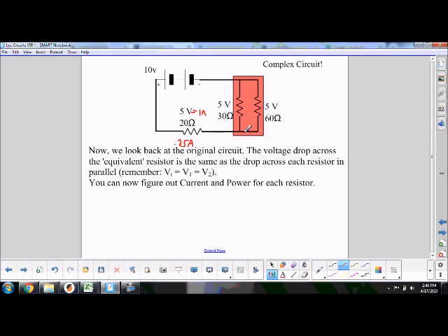Do not say, oh, I'm just going to use ratios and go with ratios. Because they're inverse ratios, bigger numbers get smaller numbers instead of the other way around. And if you had 3 parallel paths there, we're keeping it simple for starters, doing ratios with 3 numbers is a beast. So no, do not use ratios. You can certainly use ratios to double check your work and see if the numbers make sense, but do not do the work with them because it's going to be too complicated for more complex circuits. All right. So we've got an unknown current in this path and an unknown current in this path. So that doesn't do us any good.